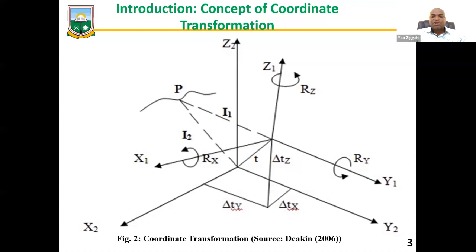No, because when you look at the ellipsoidal parameters of the War Office and the ellipsoidal parameters of WGS84, you realize that there is a difference. And that should even tell you that before we can use the GPS acquired data, which is based on a global datum, to fit into our localized system, which is the War Office ellipsoid, there is a need to be able to transfer coordinates from the GPS system onto the War Office system.